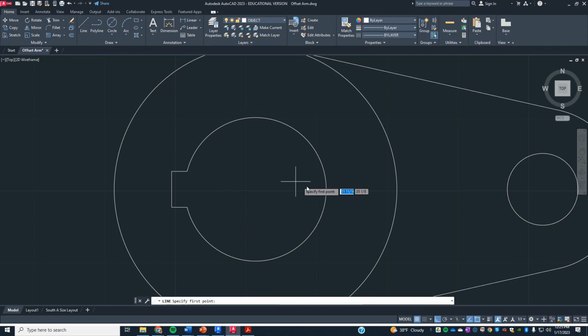On the other side, we have a keyway. It's a little bit smaller, starting from the quadrant. It comes out 1/8 of an inch. It comes over 1/8 of an inch, and then it comes down past the line. We're going to take this line here and come down 1/8 of an inch. We're just going to come past it, so it goes a little bit farther, and then we're going to trim.